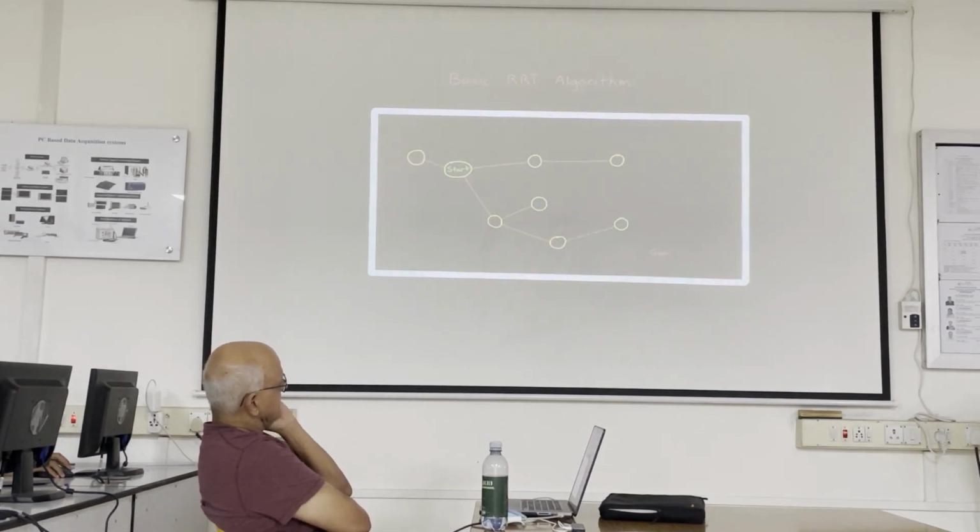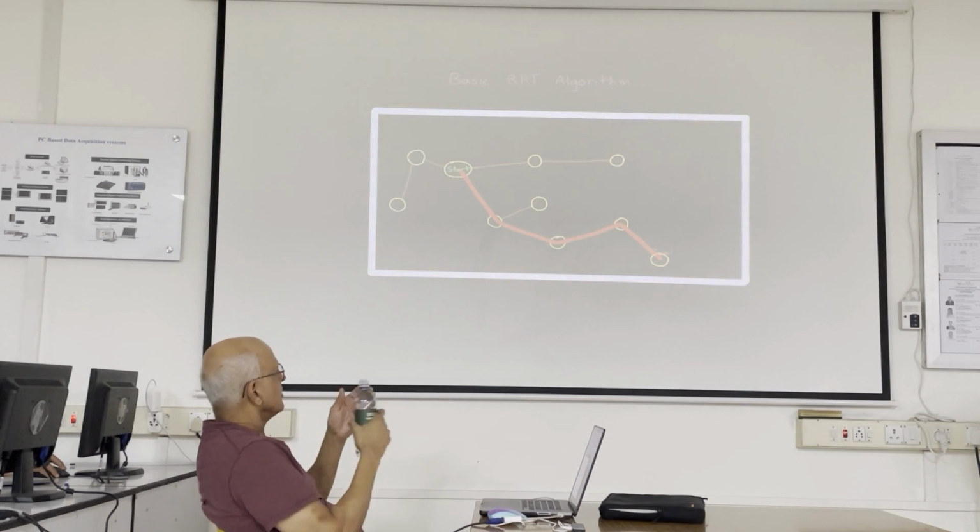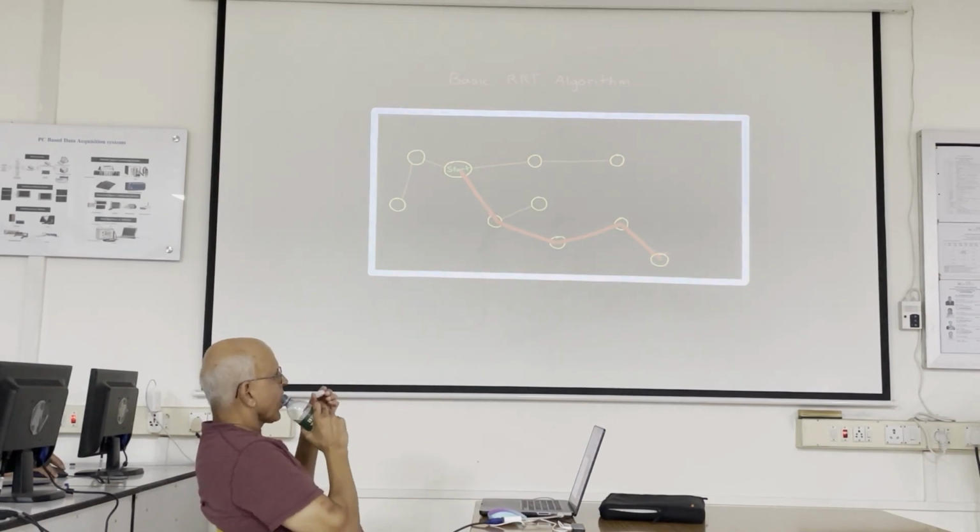Now we can continue doing this process until the path gets to within some threshold of the goal. At that point, we have a viable path, albeit probably not an optimal one, since this method tends to zigzag as it makes its way. But we did find a solution, and importantly, a solution that is likely using fewer nodes than would have been necessary for A star, since the nodes can be spaced further apart. Again, we set that with the maximum connection distance.